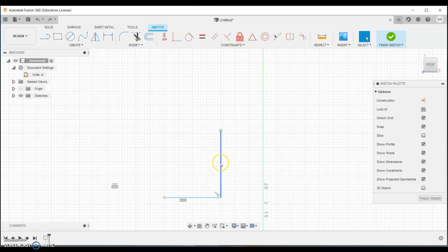So make sure you're clicking on the right parts of the line. So for example, if you draw a line and I say the midpoint of this line to that line, yeah, one error. Something with the constraint, perpendicular. This here says it's perpendicular, and I tried to make this line run along this line. You can't have conflicting constraints. If you want to delete a constraint, click on it and then delete, and that gets rid of it. So that should make it so that if I do this and this, then the midlines are connected. But once again, my original intention was to take this point and connect it to that midpoint. So make sure you're clicking on exactly what it is you want to do.